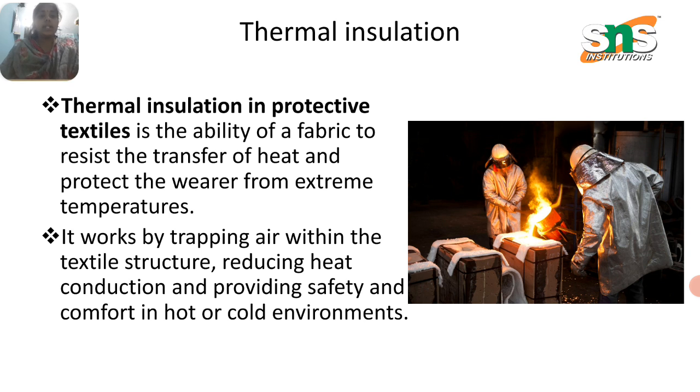Next one is thermal insulation. Thermal insulation in protective textiles is the ability of a fabric to resist the transfer of heat and protect the wearer from the extreme temperatures. So it has to protect the wearer from the heat transfer or from the extreme temperature conditions. It works by trapping air within the textile structure, reducing the heat conditions and providing the safety and comfort in the hot or cold environment.